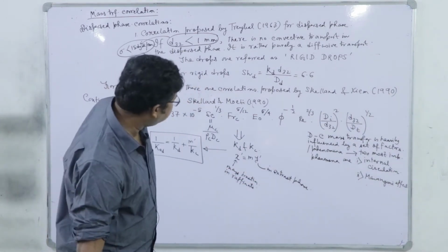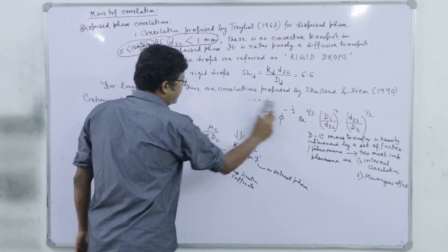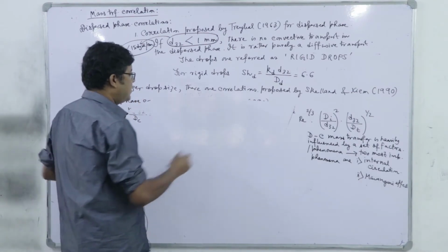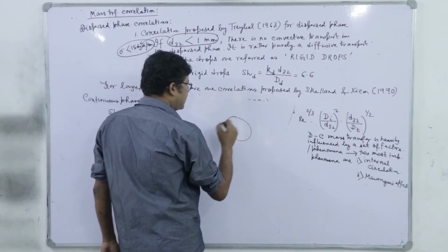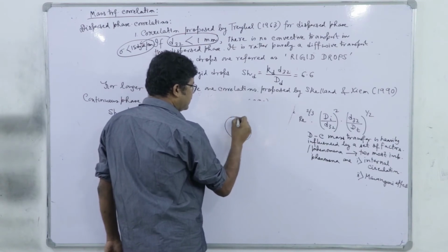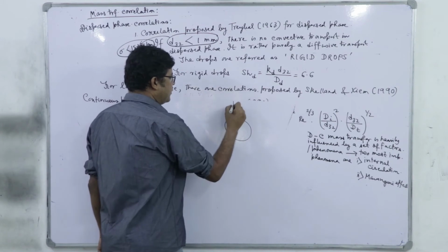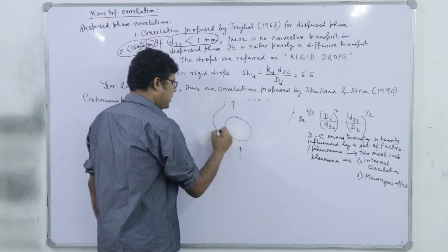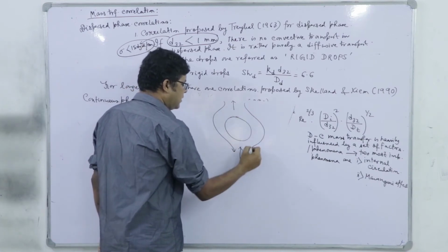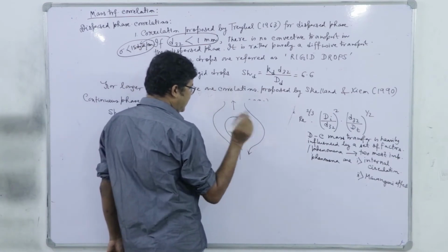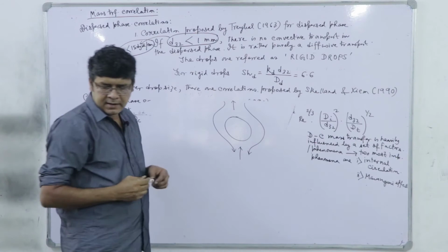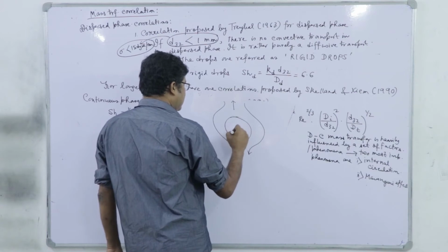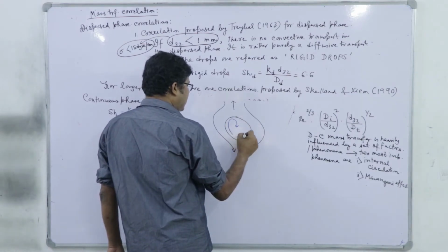So what is internal circulation? When a liquid drop of size greater than 1 millimeter moves through a pool of liquid, it displaces the liquid, and the liquid is also being continuously churned. So liquid locally will have a streamline, there may be eddies and all. Because of that, internal to the drop, we have circulations like this.